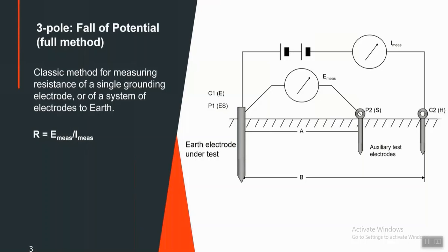Just as an overview, I believe every grounding tester in the market has the same methodology. The earth tester generates an AC signal, which is fed into the system under test, and then the instrument checks the status of the circuit for good connection, and also whether there is noise.